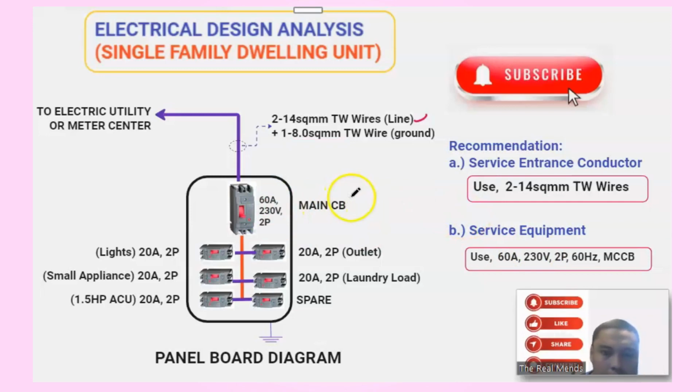And then actually for the design sa panel board, much better yung lighting is let's separate that dun sa outlet. Okay, we have this one, the panel board branch 1. This is for lighting. Panel board branch 2, that is for outlet. Okay, so for small appliance load, ito na yung 1500 VA. Circuit number 3. So for laundry loads, that is 20 ampere trip 2 pole circuit breaker.